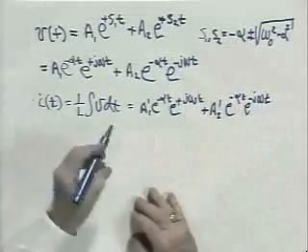And so you can now plug in the initial values. V of 0 must be capital V sub 0, the value we found from the effect of the impulse. And I of 0 plus must be equal to 0. That gives you two algebraic relationships for the constants A1 and A2. Remembering that A1 prime and A2 prime are proportional to A1 and A2, just modified by the multiplication by a complex number, gives you two algebraic equations which you can solve for A1 and A2, put them back into the original equation, collect up the assorted terms, and you're all done.